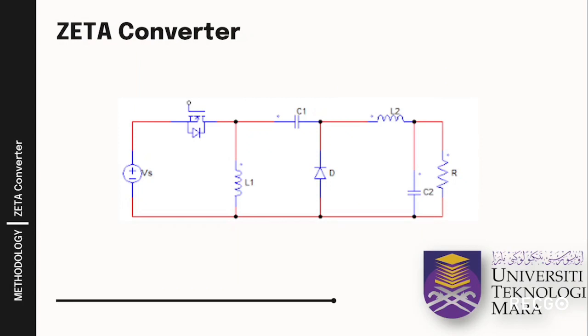Zeta converter. The Zeta converter, known as an inverting circuit converter, is made of a MOSFET, a diode, two inductors, an output capacitor, and a series capacitor. In the construction of this converter, PWM pulses are given to the MOSFET, which switches the MOSFET on and off. Unlike the boost and buck-boost converter, which invert the voltage output, the output voltage is the same polarity as the input voltage but can be higher or lower than the input voltage depending upon the duty cycle of the PWM given.